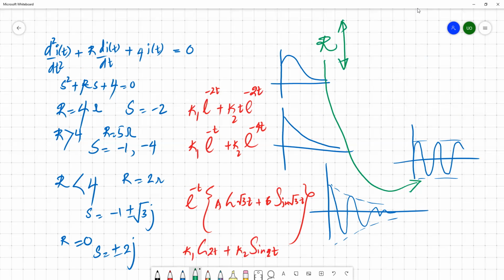So then you set it to 0 resistance. Your response is an oscillation function between +1 and -1. So by changing your resistance in this particular case, you can tune your circuit to different scenarios. The ultimate conclusion here is that by selecting a proper set of values for inductors, capacitors, and resistors, you can tune or design your circuit to operate in either way.